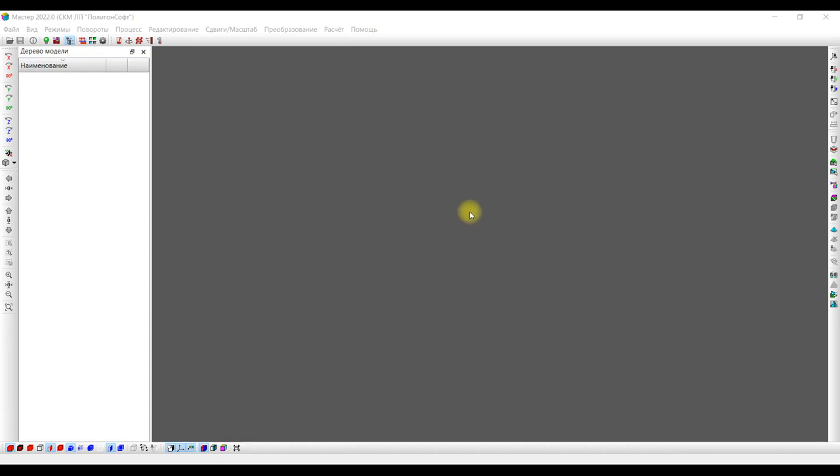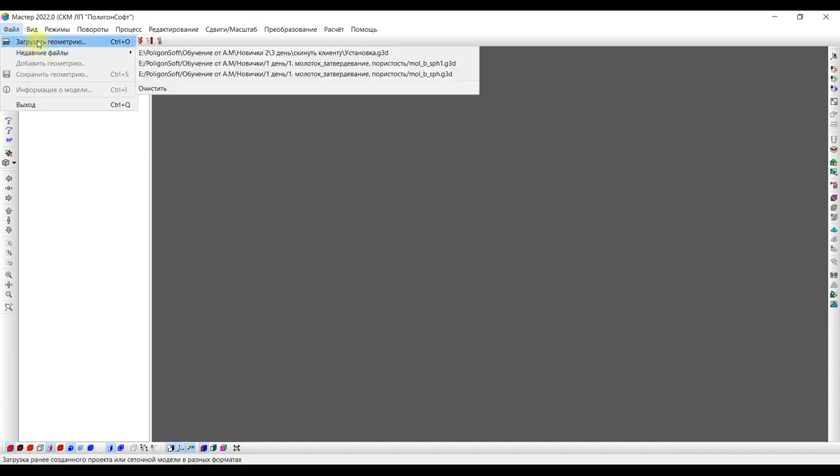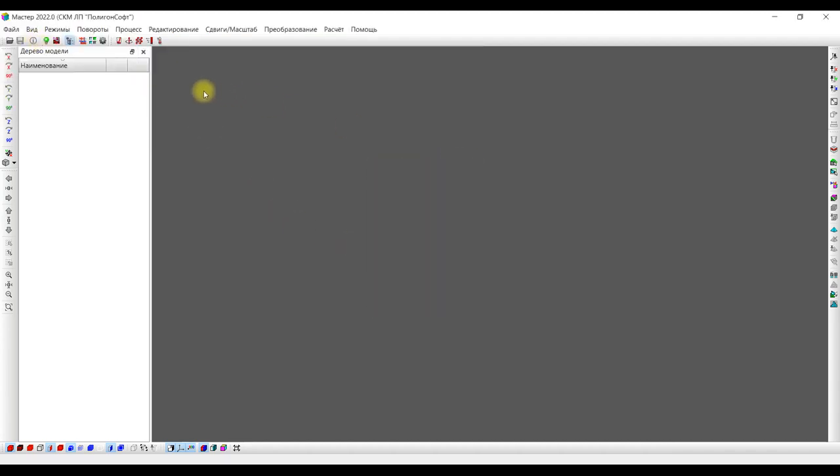In this video, we will learn how to start creating a metal casting analysis in the PoligonSoft program. We are in a preprocessor called the master, in which all the preparation for the calculation takes place, and the calculation starts directly. We assume that we already have a mesh model file, since PoligonSoft calculates the temperature distribution in bodies and solidification of the melt using the finite element method. Therefore, it will not be possible to load a regular CAD model into the master preprocessor. I will tell you how to create mesh using our mesh model in our video.